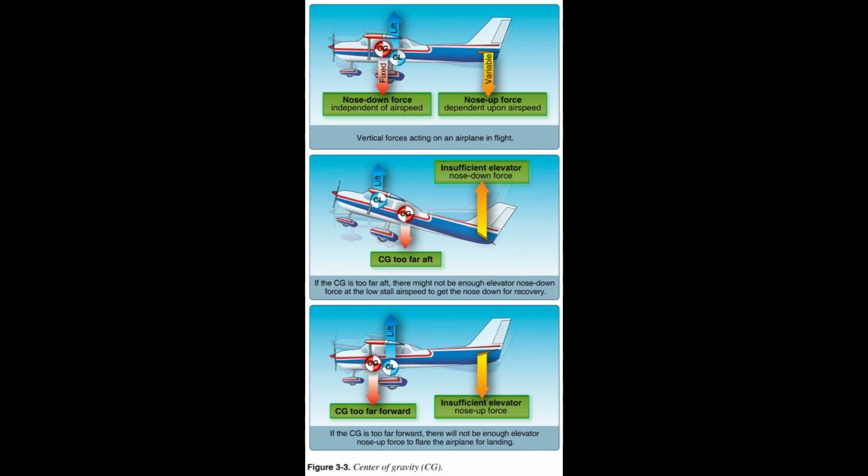One of the most significant components of aircraft design is CG. It is the specific point where the mass or weight of an aircraft may be said to center, that is, a point around which, if the aircraft could be suspended or balanced, the aircraft would remain relatively level. The position of the CG of an aircraft determines the stability of the aircraft in flight. As the CG moves rearward, towards the tail, the aircraft becomes more and more dynamically unstable.